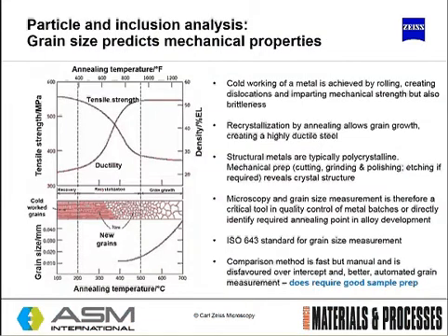So let's see how that translates into the recrystallization and the treatment parameters. Well, clearly, tensile strength and ductility are very closely proportionate to the grain size within the steel billet itself. So the cold work grains, which might have been freshly rolled, are then heat treated or annealed, and clearly you see the growth in the grain size.